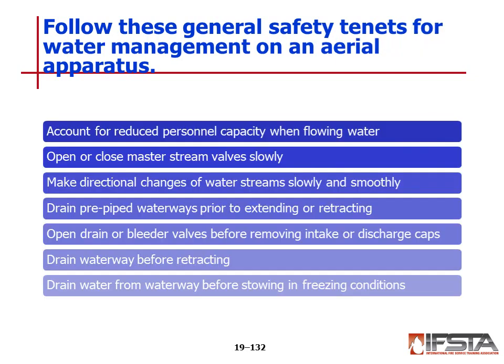Follow these general safety guidelines for water management on an aerial apparatus. Account for reduced personnel capacities when flowing water. Open or close master stream valves slowly. Make directional changes of water streams slowly and smoothly.